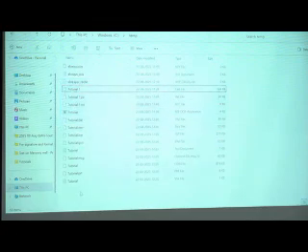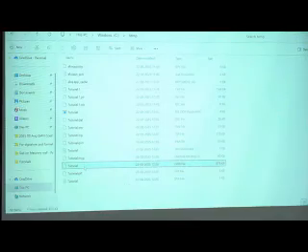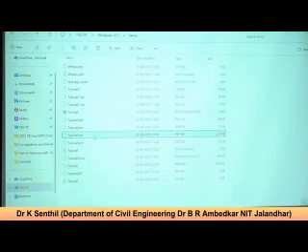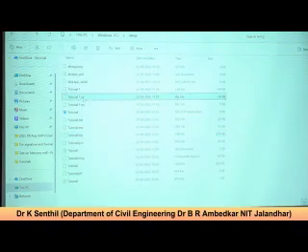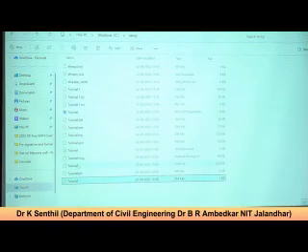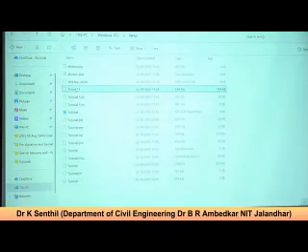In the supporting files, of course, you have to note that there are 5 files that are very important. Let's talk about the ODB, the output database. This is the first important output file. Second is .inp, the input file, and then this JNL journal file, a supporting file of CAE. CAE is this one. So these 5 files are very important, including the status file.